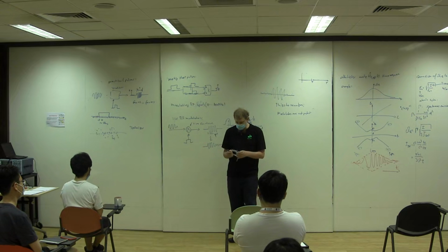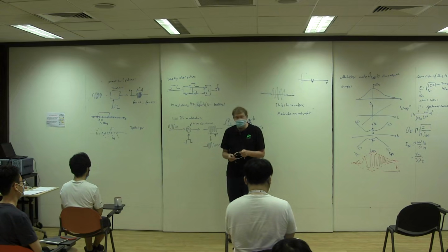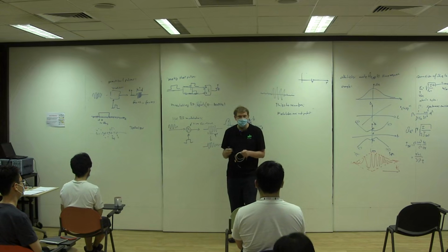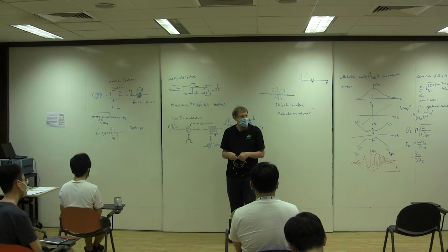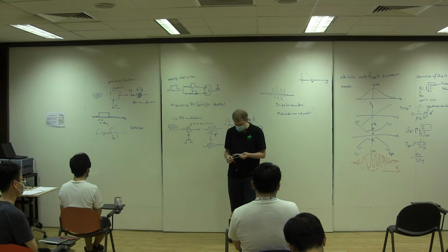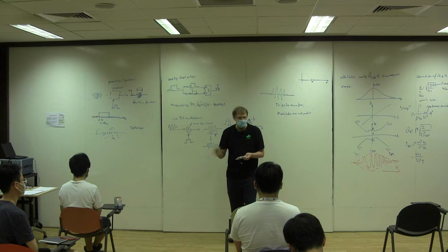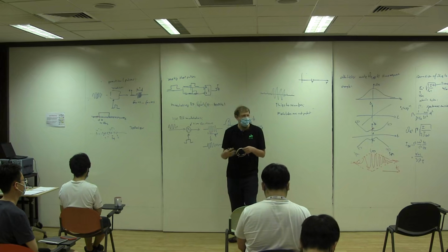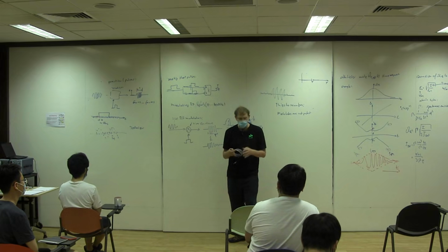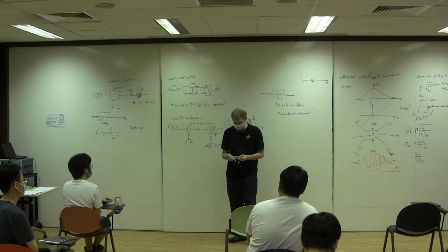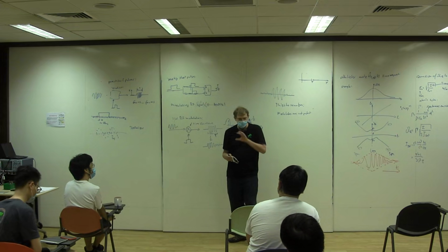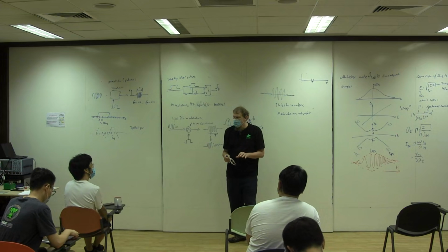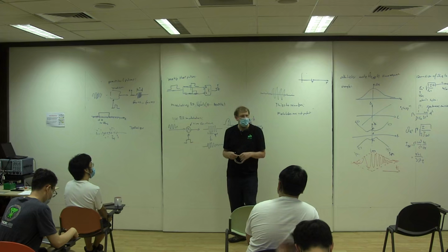You can do this with coaxial cables. They have well-defined propagation properties. You can use twisted cables. That's what your Ethernet cable does, or your USB cable, or your plain old telephone cable, twisted pair things. Okay, they have an impedance of typically 100 ohm, plus minus something. So it's still not so easy to transfer signals from A to B through such cables. Yeah, so a lot of work when you work with fast pulses goes into making sure that you can bring your signal from A to B in a way that doesn't disturb pulses.